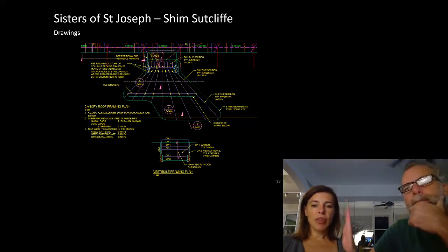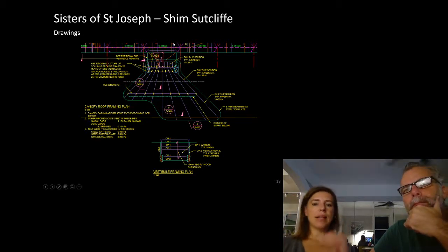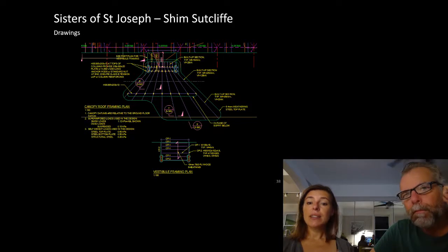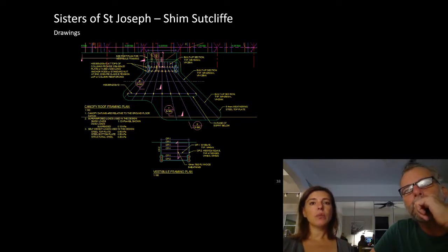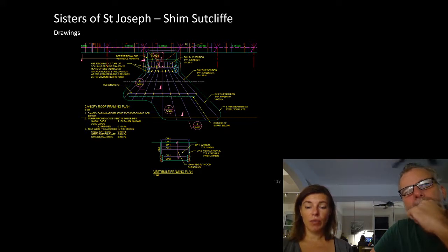Now there's a few reasons there. That was next to a high-rise building and a very small canopy. This is against a relatively low building, and this is at the 2nd floor of the building, so that's part of the calculation for how much snow load falls down on it. This is also from an older code. So this was based on not even the 2010 building code, but the 2005 building code, which was OBC 2006. So 5 for the national and 2006 for the provincial, which had much more lax accumulated snow load criteria.